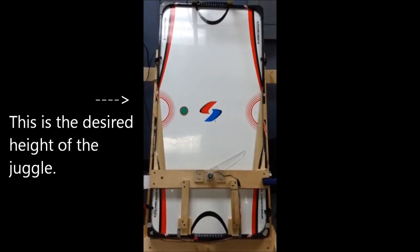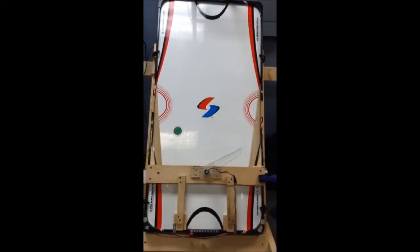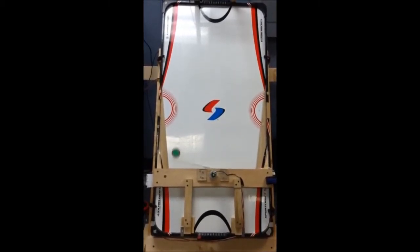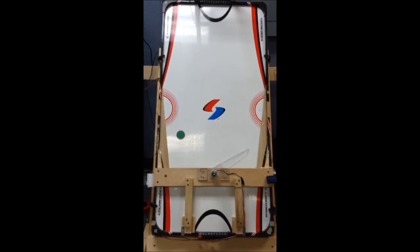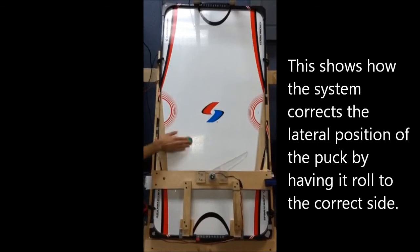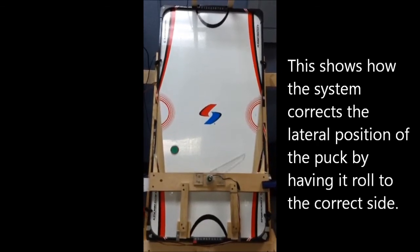For the revised mirror law, the major X correction is hard-coded to move the puck onto the correct side of the table. If the puck is falling, the paddle goes to 0 degrees to stop the bouncing and prevent the puck from falling below the paddle. The paddle then raises up to roll the puck to the right side. This allows us to use a smaller X correction gain to produce a much more stable juggle.